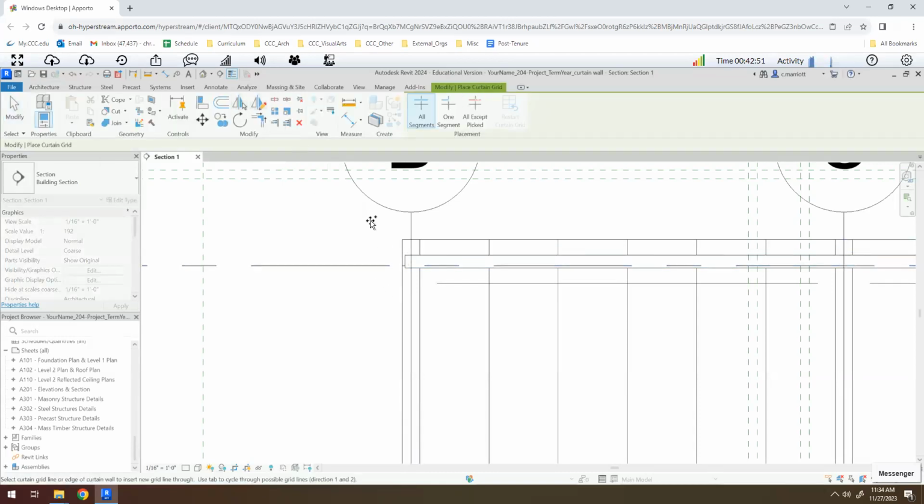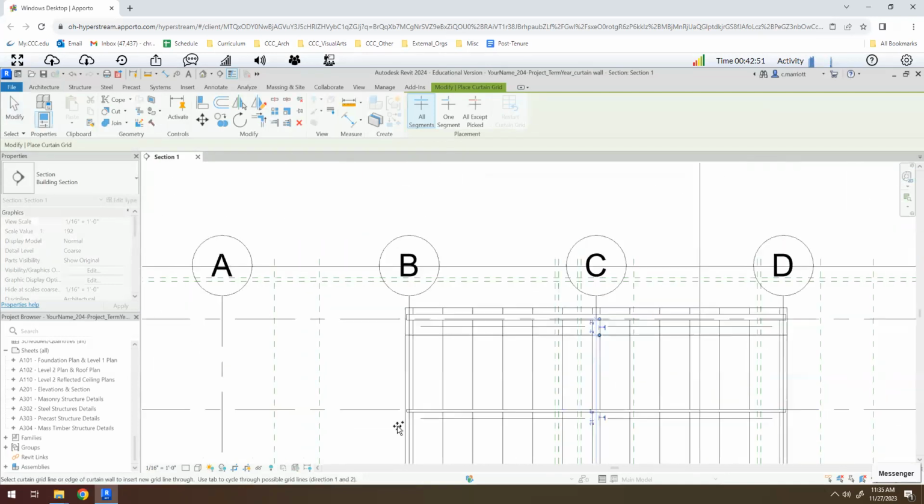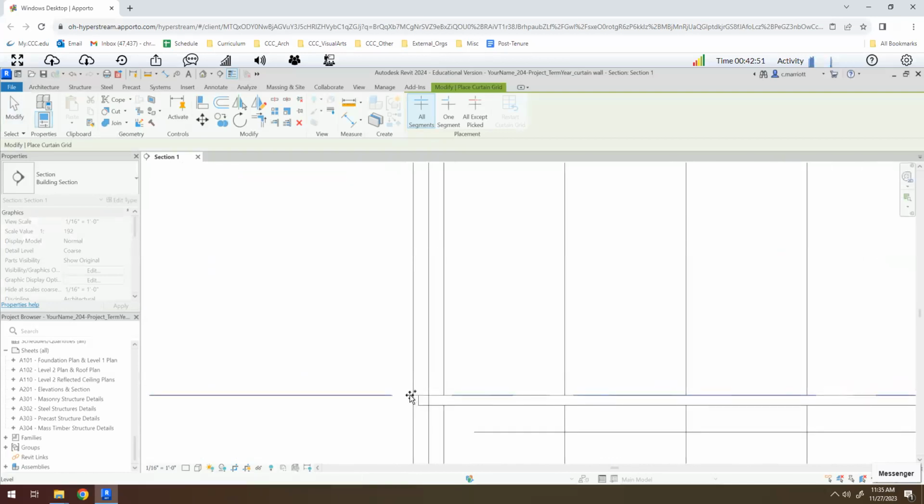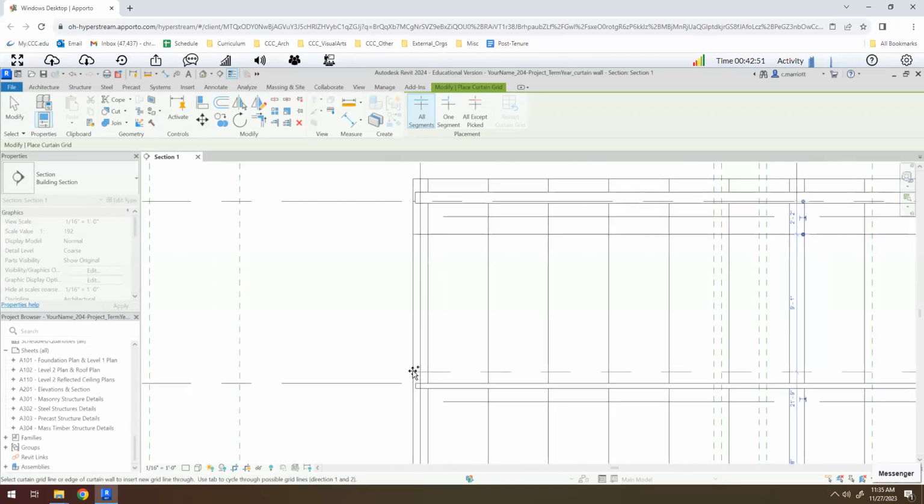So I'm hovering over towards the left here. I think what I'll do, there it goes. Okay, now I'm seeing it relative to that datum line. So 2 feet 2 inches below. Okay, now I'll continue making these. Now this top one, or the one at what's level 2, I want that one to be a foot above level 2 datum. So let me go ahead and just place it there, and I'm going to have to move it.